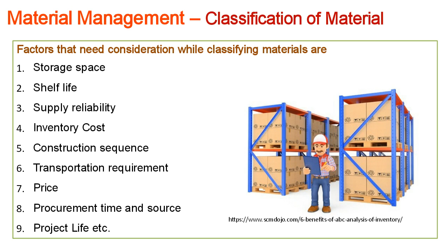Whereas there are some philosophies about storing everything, all the finalized goods stored in a place. That will require more space, and it will consume more resources. Then shelf life: for some materials shelf life will be very short, for some it will be very long. Say in cement there are criteria that it should not be used if it is stored beyond a certain period of time. And for rebar we'll have to apply some non-corrosive coatings, otherwise it will get corroded. Whereas some other materials, like our basic building blocks, will have more life.